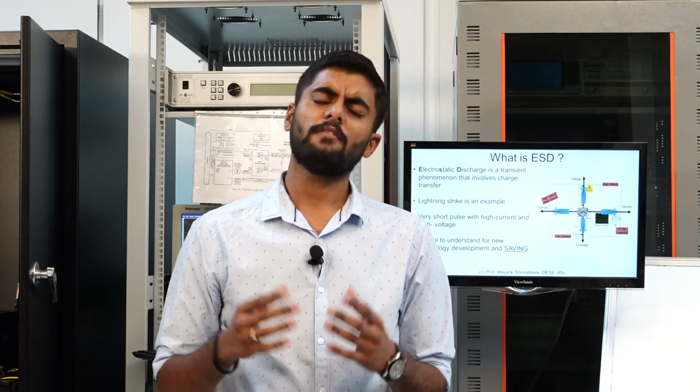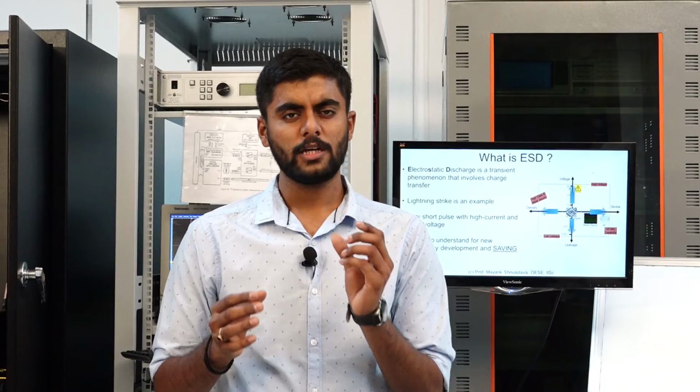ESD is, as I said, charge transfer from one body to another, and in microelectronic cases that involves a very high voltage amplitude, a very high current, and a very short time period. The time periods we talk about are in the range of 100 nanoseconds or so. As human beings, you don't feel charge transfer taking place in your body all the time, but in microelectronic devices, it becomes very important.